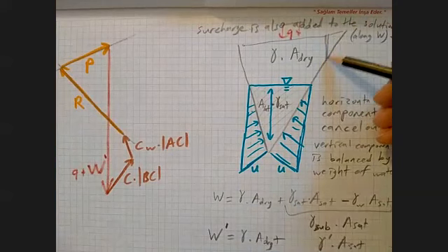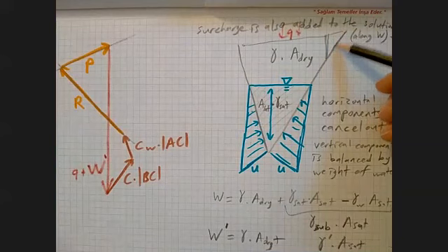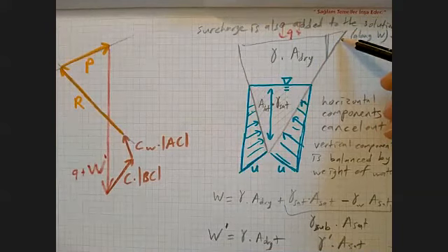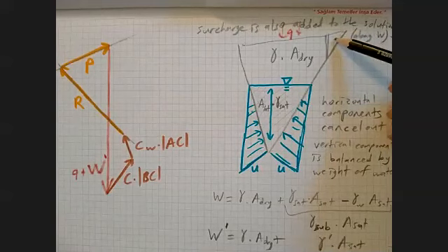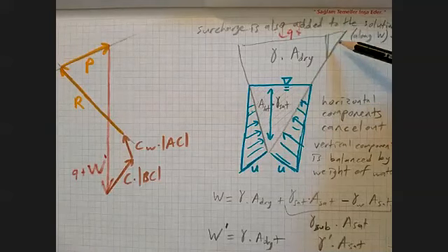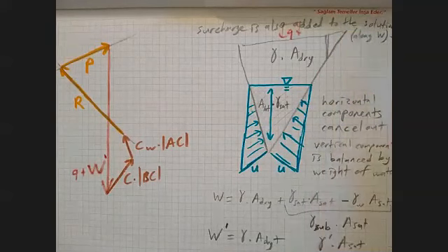It's not going to provide the strength from this length of soil interface. Of course, its weight will not be pressing on my wedge either, but this shear strength contribution is greater than what the weight does to destabilize it.